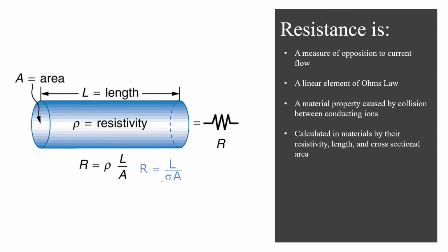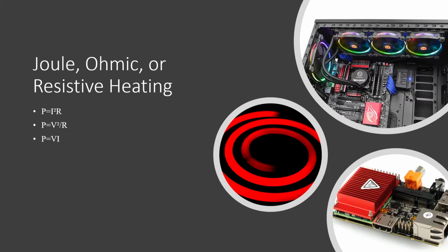current flow. Joule heating is a product of Joule's first law, stating that heating power of a component or conductor is proportional to its resistance times the square of its current, or any other form of P equals, using Ohm's law. This effect of resistance is most notably employed in electric heaters and stoves. However, often this resistive heating is not a desirable effect, and components like heat sinks, radiators, and fans must be employed to keep electronics in safe temperature levels.